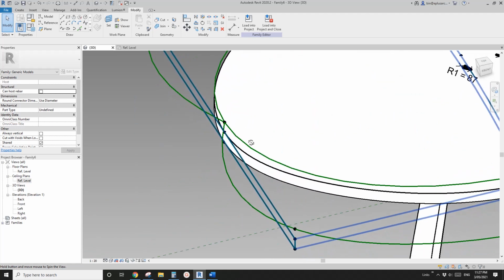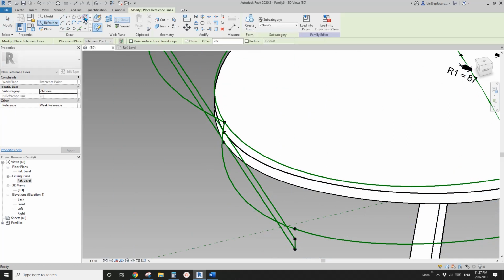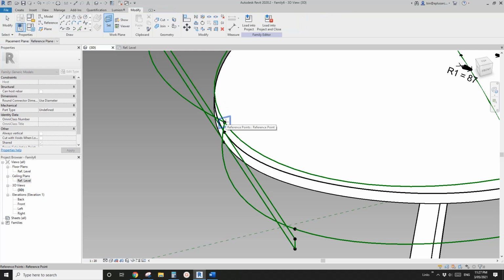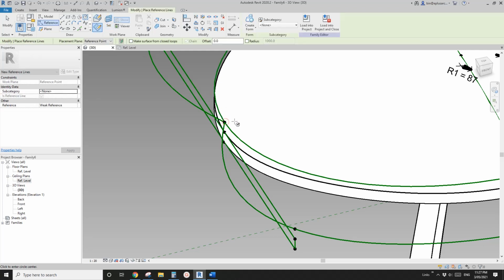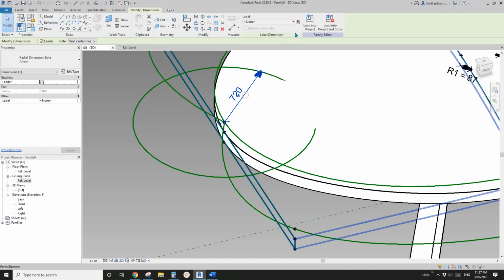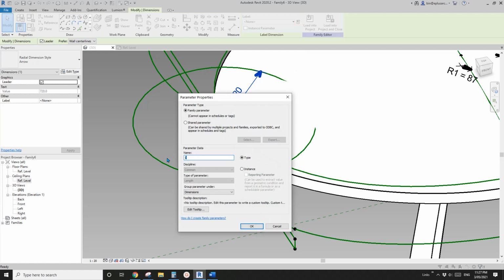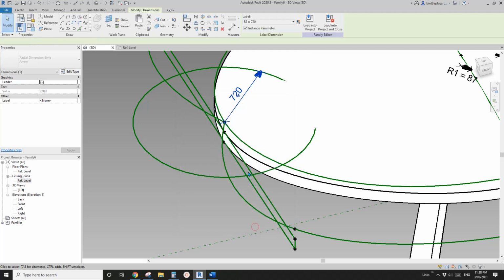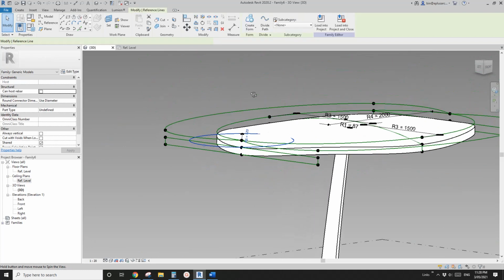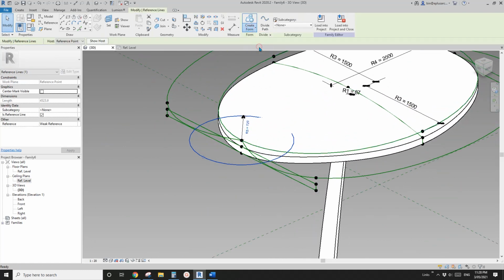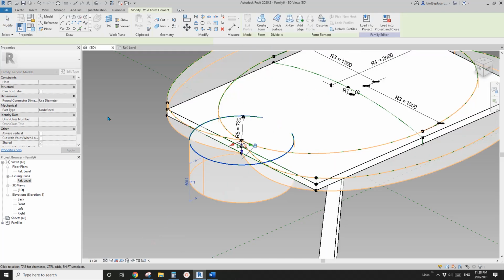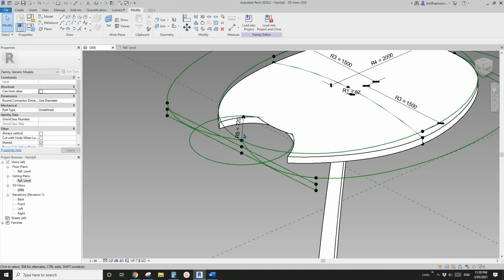So I'm going to create a void on this point. Okay, reference circle. I'm just going to use a circle for that void and draw on the world plane. Set the world plane, pick the horizontal world plane, so Tab, so this one. I'm going to create a circle and add a radius. This time I'll just create an R5 instance and OK. Now select this one, and it's the same. I'll create a void, a solid void, and then I'm going to, oops, sorry.